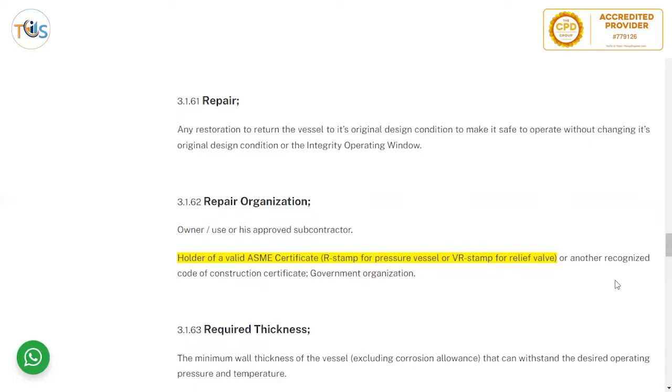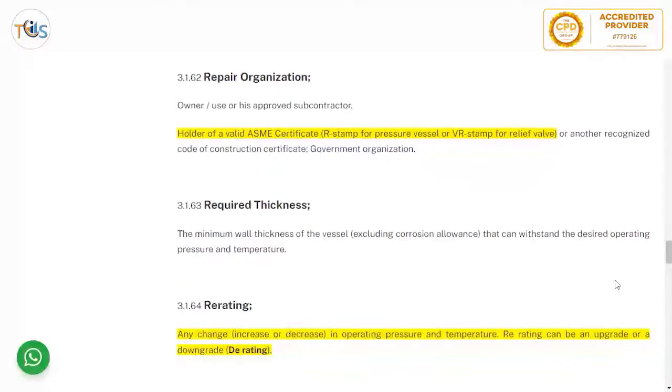Alteration always would follow the hydro test to validate the overall work, to validate the design. Repair does not necessarily need to be hydro tested unless the inspector feels the hydro test needs to be done after the repair. And if you're doing a hydro test as an API inspector, you're recommending, you need to consult with a pressure vessel engineer.